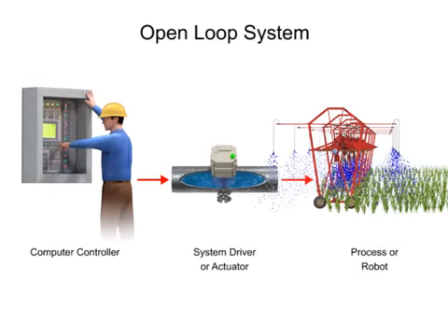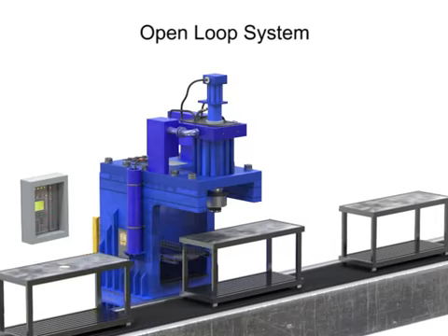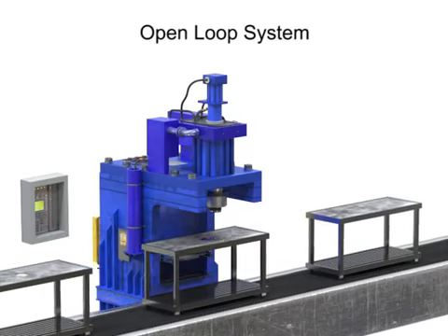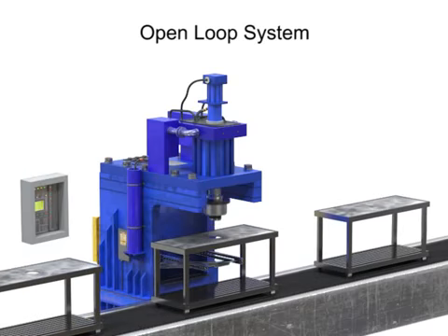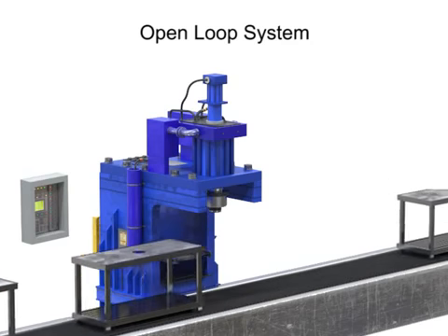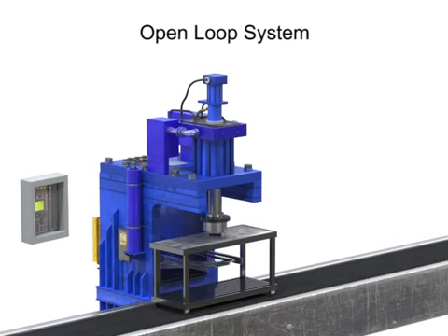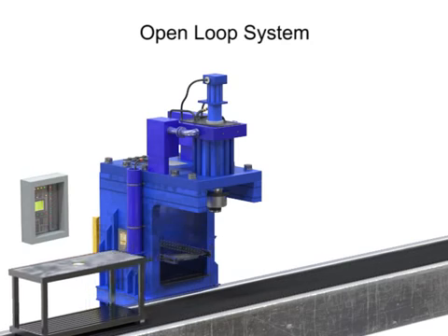Some good examples for open-loop control systems are stop-and-go conveyor systems with constant loading, and manufacturing applications with high repeatability and low variation, such as punching holes out of a piece of sheet metal or reorienting workpieces. Material handling and machine tending operations also account for many open-loop design applications. Due to their lack of speed control and lack of flexible work positions, open-loop control is useful for well-defined systems where the relationship between input and the resultant state can be modeled. The positions of the robot can be predetermined and the loading environment does not change.